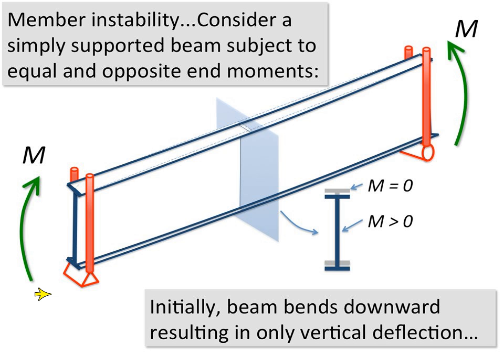Now the top flange of the member is all in compression, always, and the bottom flange is always in tension. Another important thing in my diagram, and this is essential here, is that the ends are braced. If they weren't braced and we put any type of load on here, there's a good possibility the beam might just tip over, fall over in the minor axis direction. But we do have these rods here that symbolically represent the fact that the ends of the member are prevented from twist.